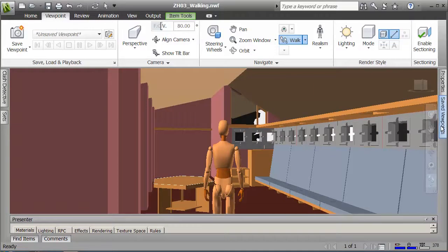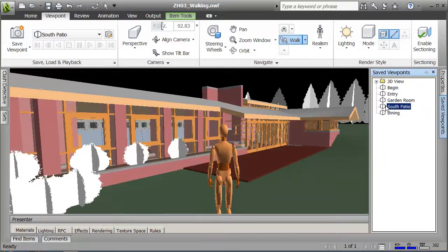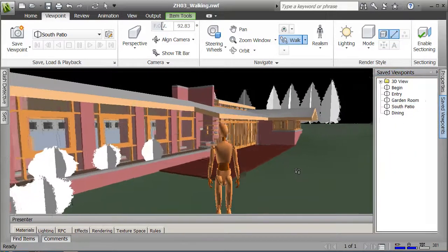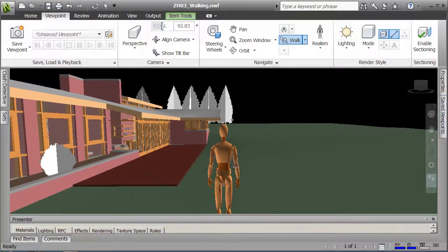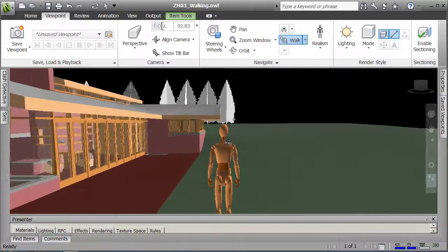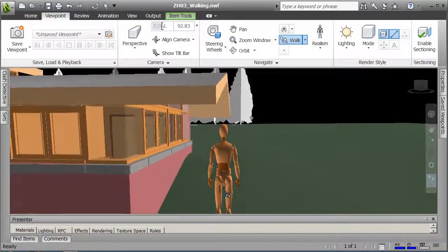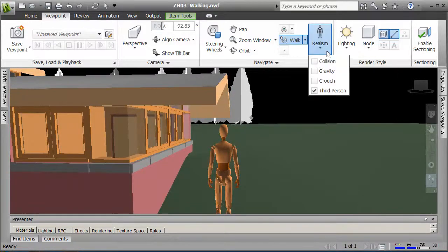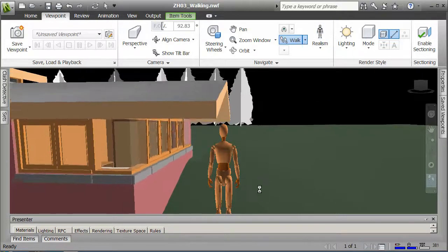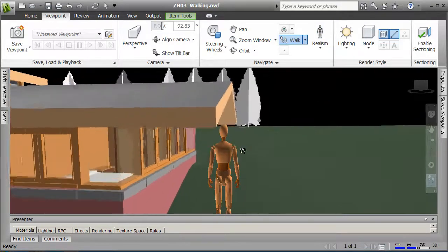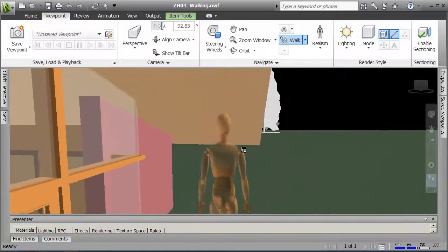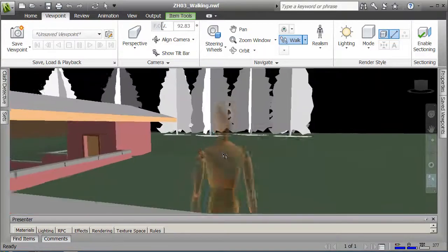The main point here is that I don't need a finished Revit model. I can link in the NWC file, this output from Revit, and then as the project is updated, so is the building in Navisworks. So I could work collaboratively instead of waiting for somebody to finish the building before I get in and check things out.